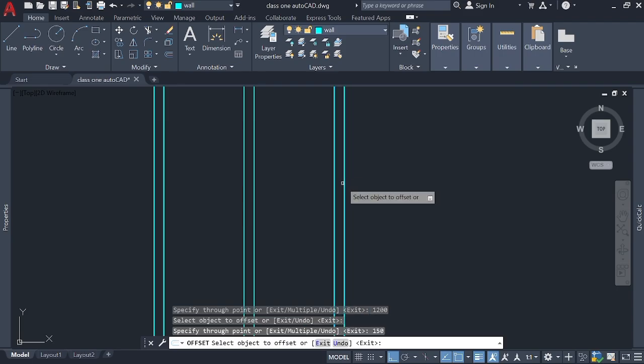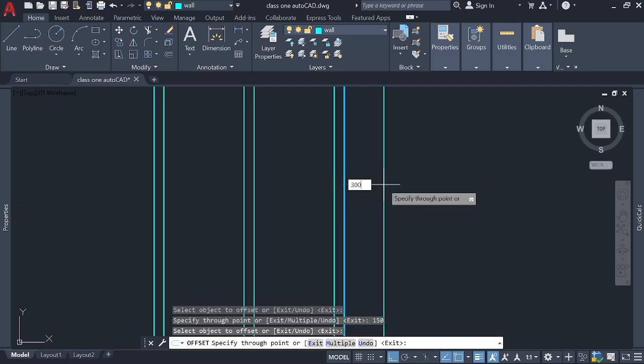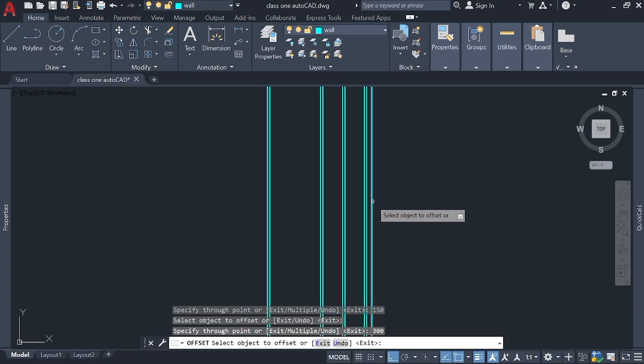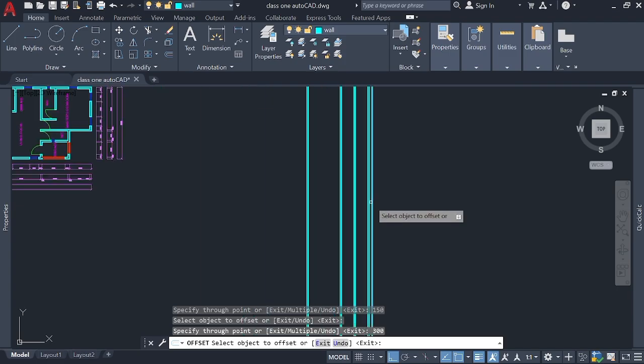Enter. Then the next room is 3000 millimeters. Note all our dimensions are in millimeters. You click on it, drag out 3000, enter. So that was not correct. All right, let me teach you something. In case you make a mistake, just like this now, I wanted to press 3000. I'm sure I inputted 300 because it's showing 300 here on the command line.